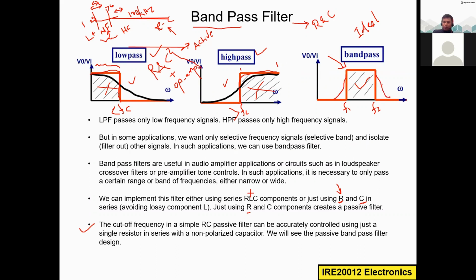And we know the falling range, this is called the roll-off, or we can also call this the fall off. So this is minus 20 dB per decade. Okay, so this is the actual or practical band pass filter response.